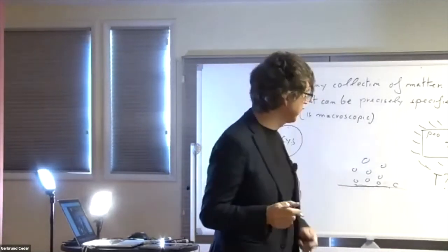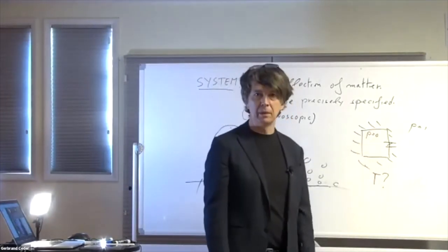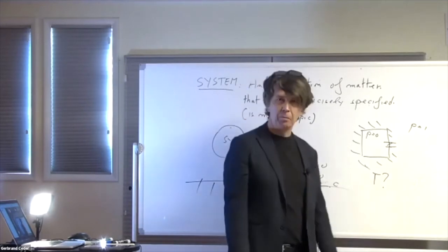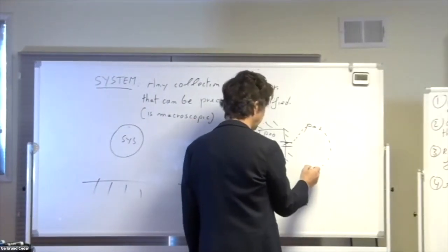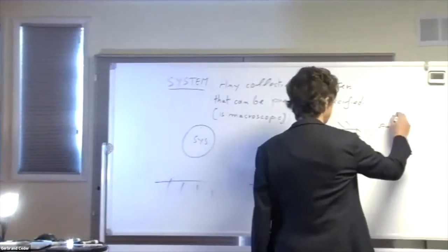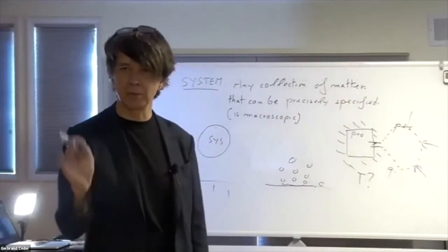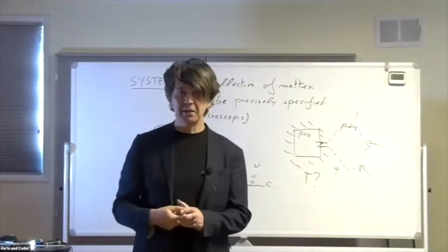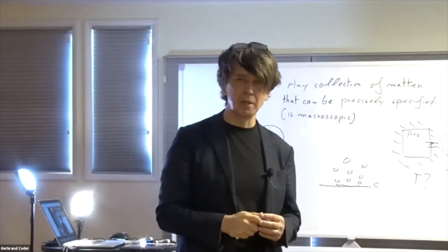There's many ways you can solve this, right? You just have to know what you're doing. Maybe your logic is to take the tank as a system. If you take the tank as a system, then it's an open system, right? We'll talk later about what open and closed means. But the easiest solution is to imagine the gas that ends up in the tank before it's there. So this balloon of gas that forms and that gets pushed into the tank. If you take that as your system, you'll find this question takes 3 lines to answer. You can also solve it taking the tank as the system, and it's a very different approach. And of course, it should give the same answer. But what I'm saying is, make sure you know which one you're taking. Okay.